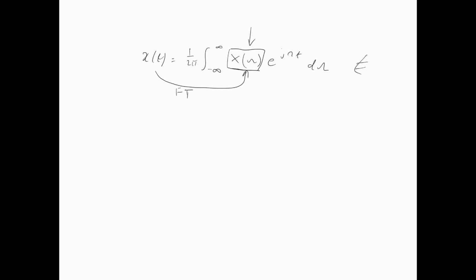And it turns out that the expression for the Fourier transform is very similar to the expression for the inverse Fourier transform. The consequence is that we have some sort of duality going on, where results in the time domain have analogues in the frequency domain, due to the fact that these formulae are so similar to each other. Here's the explicit formula for the Fourier transform, and to emphasize, its use is that it gives us these coefficients here that we can substitute into this inverse Fourier transform representation of an arbitrary signal x of t.